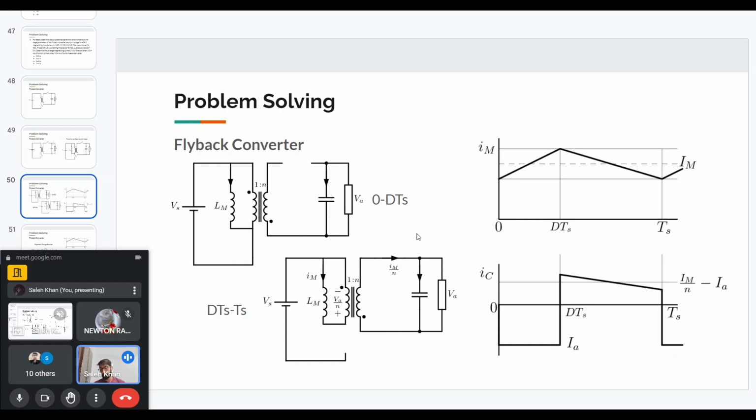It is not very simple. If we instead have an isolated converter, the turns ratio will give us some step down itself, and then we can have a medium duty ratio of 0.5 or 0.4, which is easier to generate and maintain. So that is another reason why we use isolated converters.